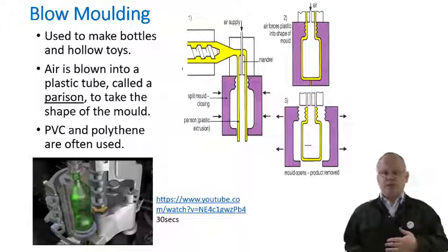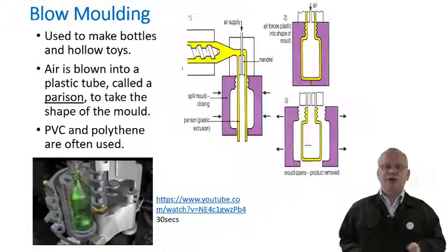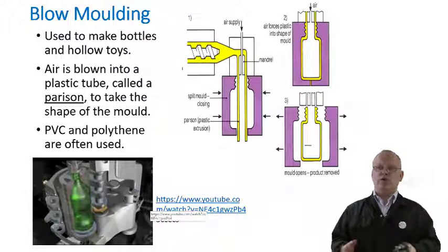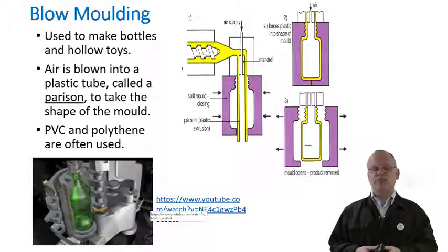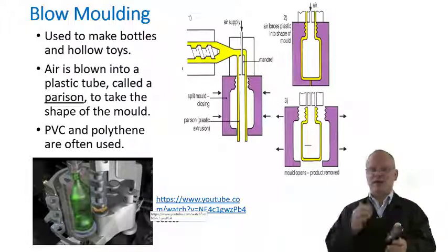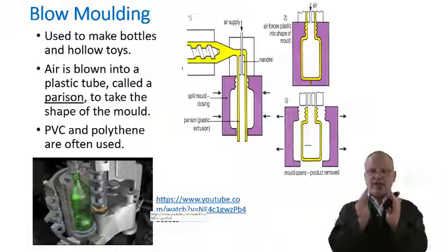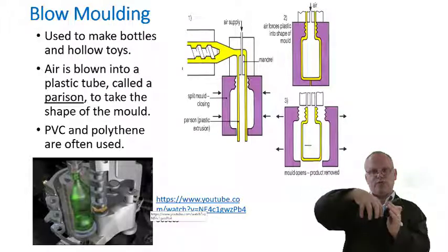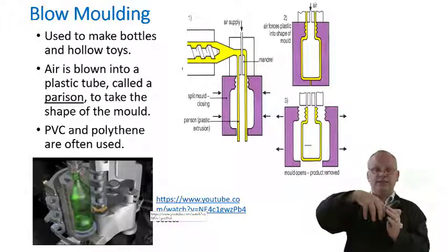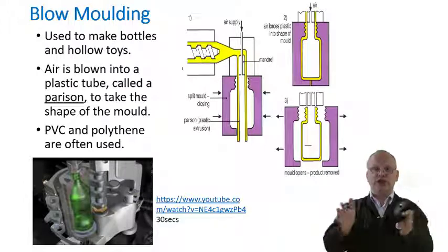Quick one about blow moulding then. Blow moulding is a funny process that you would not really think about if you weren't made aware of it, but it's used in so many of our products, and there are two distinct ways of doing it. Both methods that we're going to talk about today involve a space which has a tube of plastic, a tube of polymer inserted into it, and it's then forced outwards by pressurized air.